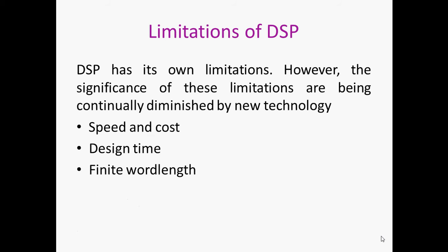Finite word length problems. In real-time situations, economic considerations often mean that DSP algorithms are implemented using only a limited number of bits. In some DSP systems, if an insufficient number of bits is used to represent variables, serious degradations in system performance may result.